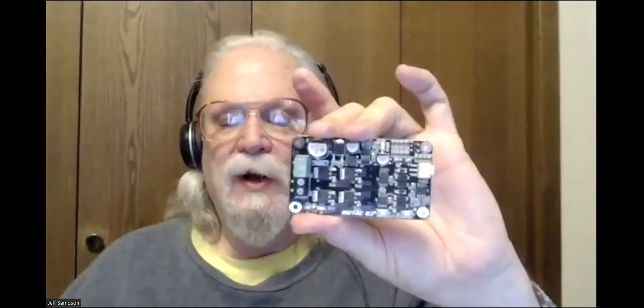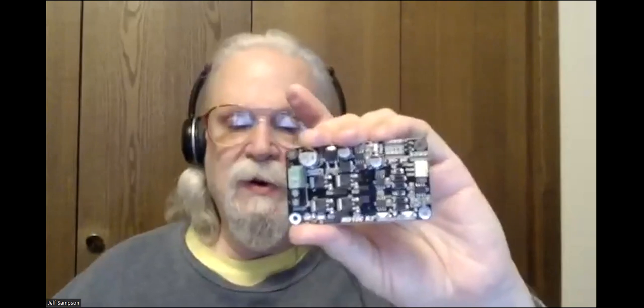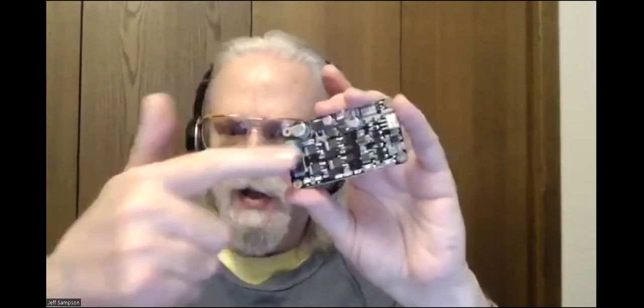He said, I should let him tell the story, but I'll tell it anyway. He set it up, and he got it to run. He could push the buttons, his motor would turn. He hooked up his microcontroller, and nothing. It wouldn't do anything. So I was out digging, and I found some tutorials where they're showing that the ground wire between the logic and the battery, they had them hooked together. They specifically said hook those together. And my thought was it's probably connected on the board, so you shouldn't have to do that. But he hooked them together and it started working. And he disconnected it and it still worked. So we were baffled on that.